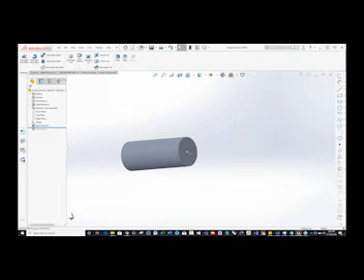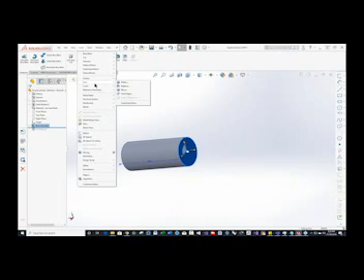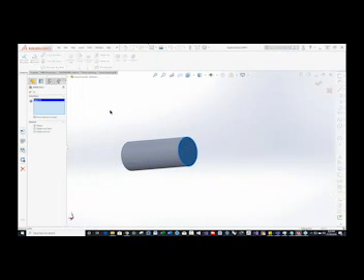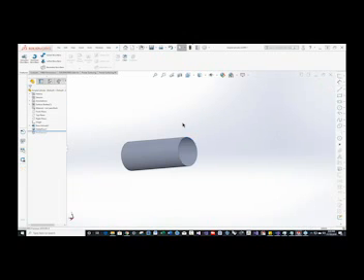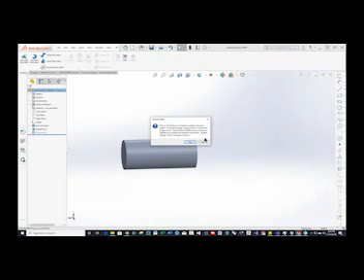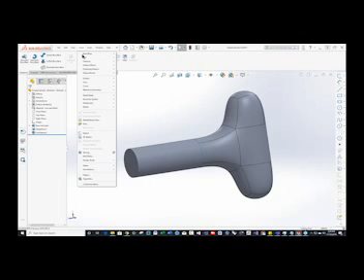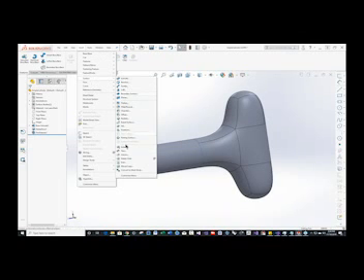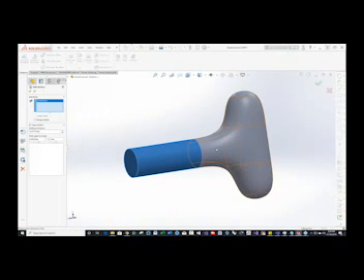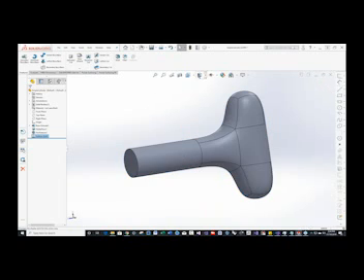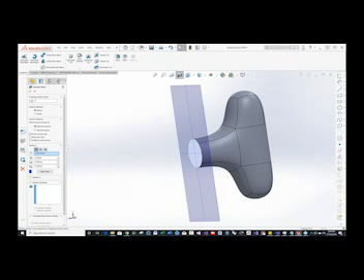What I want to do is delete this face, insert face, delete the face, so I'm making it an open shell. Then if I pull back down with my power feature, I should now be able to go to tools, surface, knit, and I will try to create a solid. And you can see we now have a nice solid here.